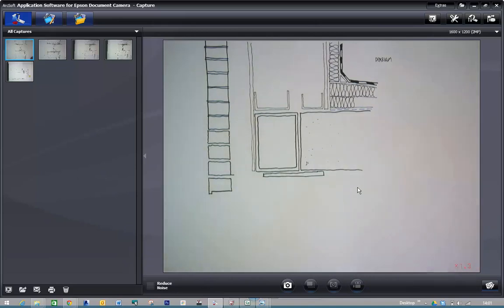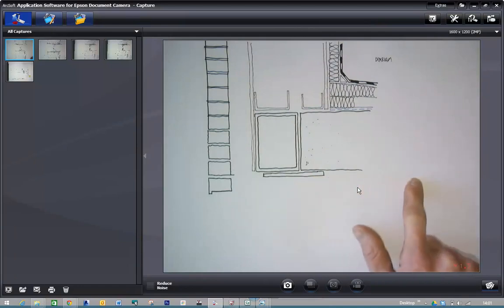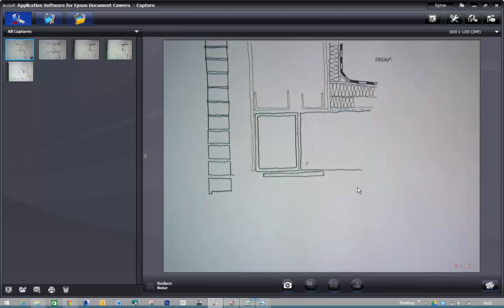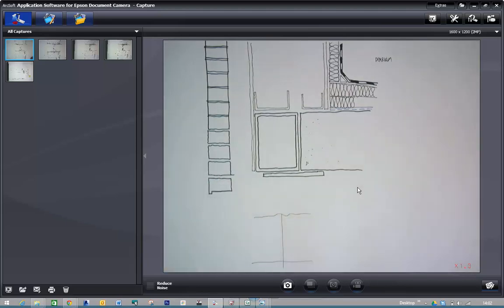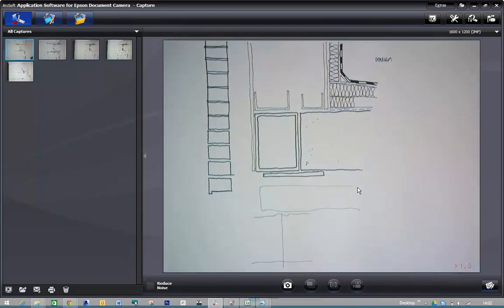What we did achieve was we did get our exposed concrete soffits. And by using this slim floor, we did get our thin floors rather than doing a kind of conventional steel frame with the concrete sat on top. So, we were happy. We've got the environmental benefits of the thermal mass.